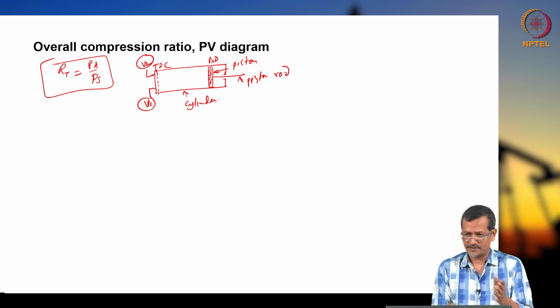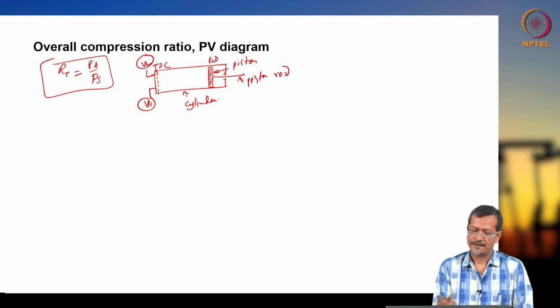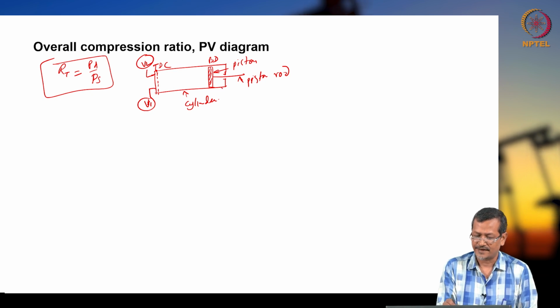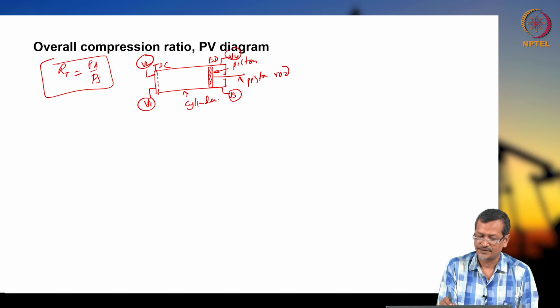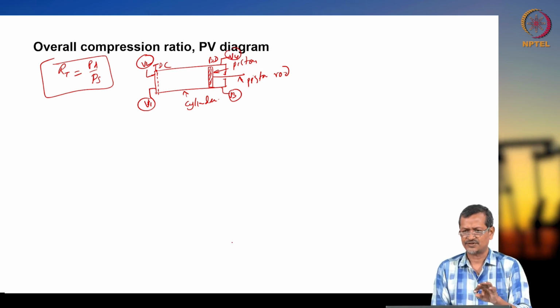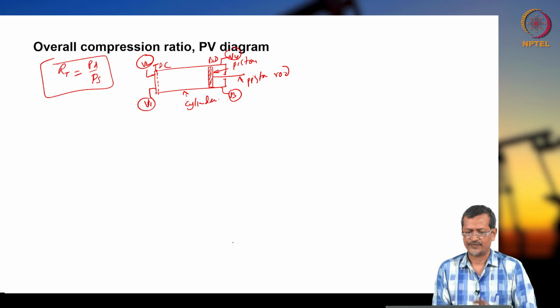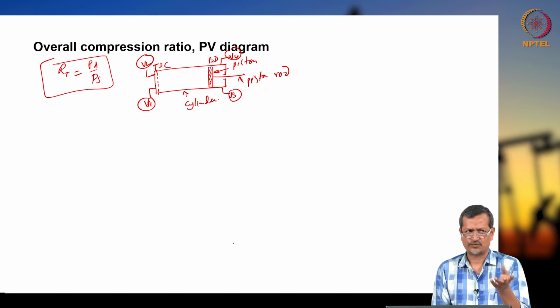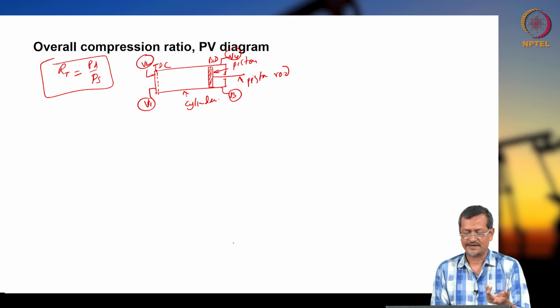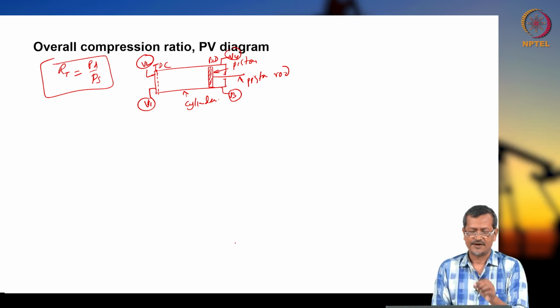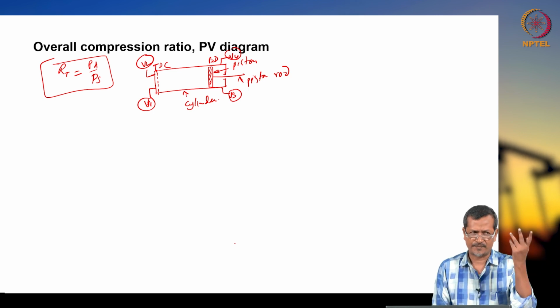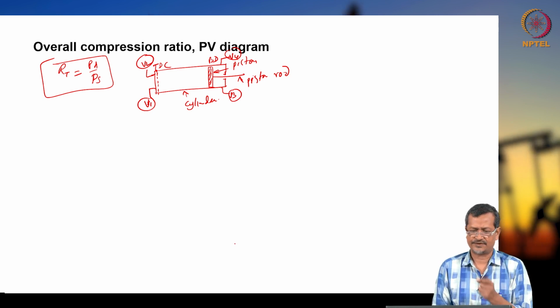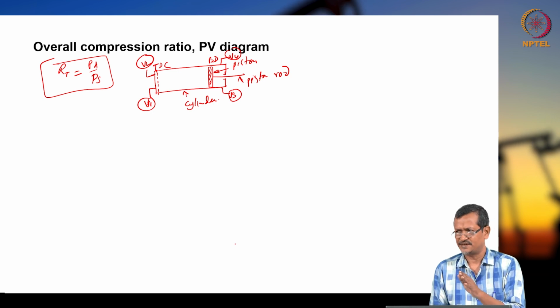So we will have two valves mainly if we have a single acting cylinder. If you have double acting, then I will have more valves: V3 will be there, V4 will be there. There is no specific nomenclature, I am just putting my own names, V1, V2, V3, V4. And if the piston has a certain amount of leakage, you can consider 1 to 3% within that range. If a very high amount of leakage is there, then you have to change the cylinder or piston. For small leakage like 3 to 5% it is okay. For sucker rod pumping also we normally assume that much leakage. So in any compressor system that much leakage is normally allowed.